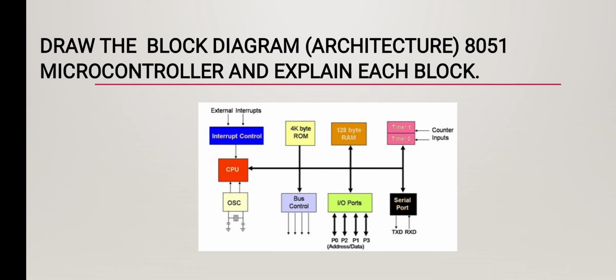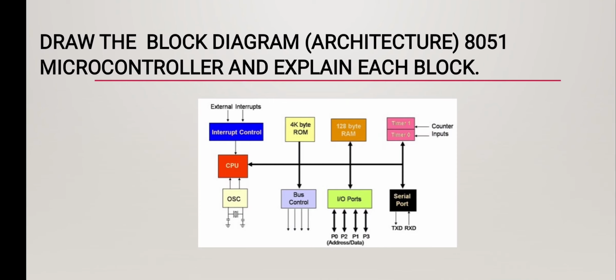So what is interrupt control? As its name suggests, an interrupt is a subroutine call that interrupts the controller's main operation or work and causes it to execute another program which is more important at the time of the operation. The feature of interrupt is very useful as it helps in case of emergency operations. An interrupt gives a mechanism to put on hold the ongoing operation, execute a subroutine, and then resume the previous operation.